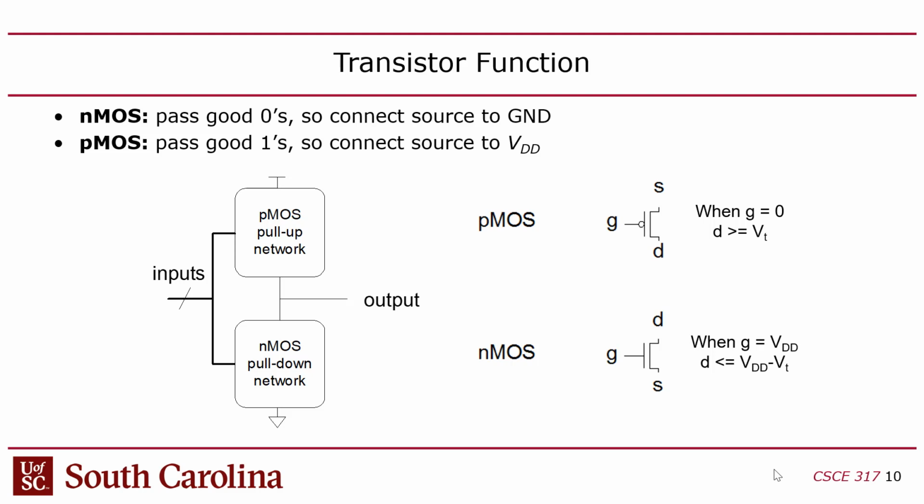This is the same thing we talked about with the push-pull drivers when we were talking about SPI. You're always shorting the output of the gate to the power supply, or shorting it to ground, depending on what inputs you're putting in. But they're mutually exclusive. There's always going to be one of these on at one time. Make sense?